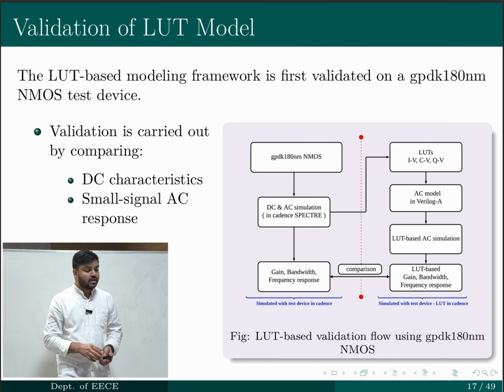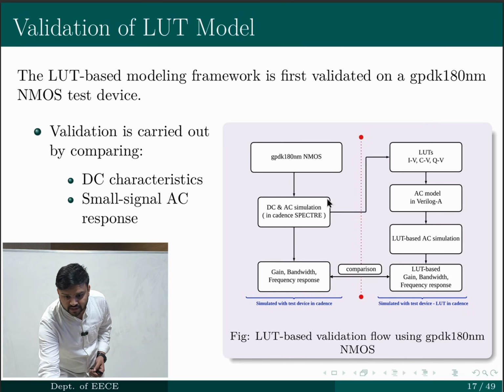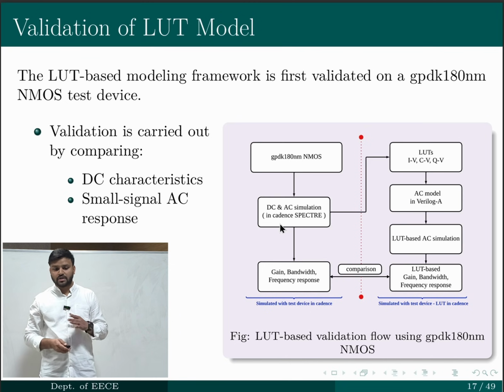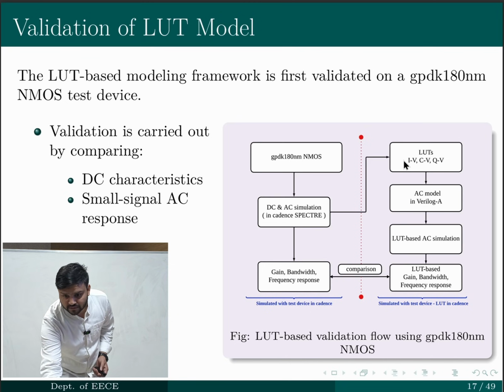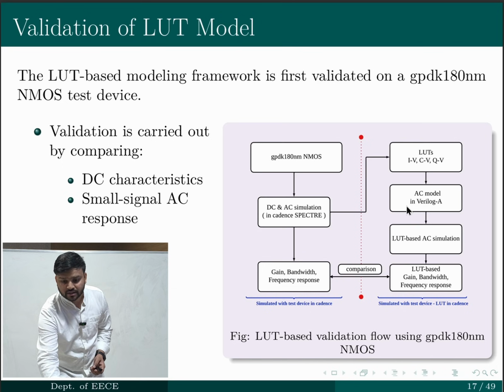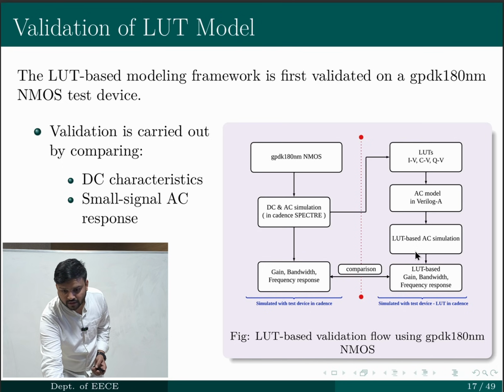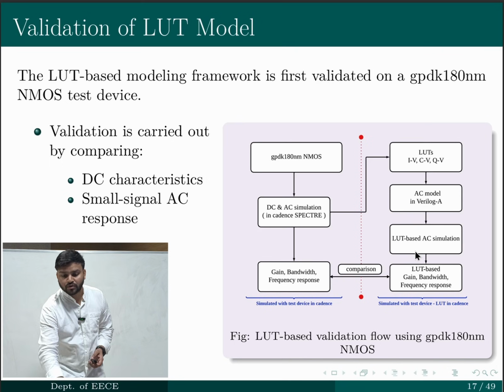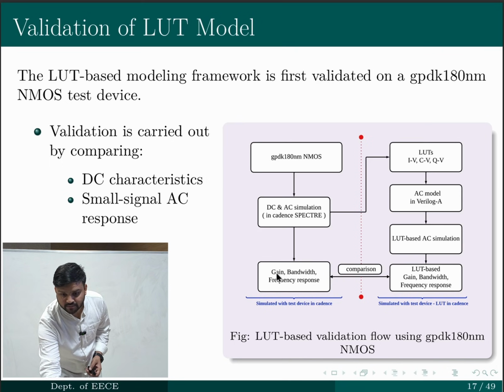Then from the test device's simulated DC and AC characteristics, the characteristics are stored in tabulated form, which is the LUT, and this LUT is given to the Verilog-A, and this Verilog-A is simulated with the simulator, and then the results for the same biasing condition are compared.